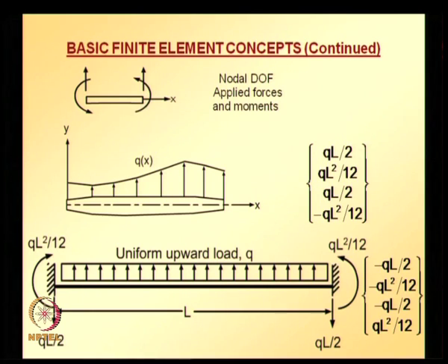So this is about the physical interpretation of equivalent nodal loads. In summary, finite element equivalent nodal loads are simply fixed end forces with sign reversed.